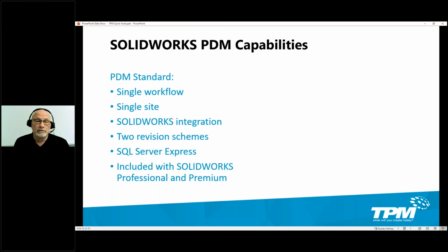It's a single site application. So if you have multiple plants where you need access, you couldn't use PDM Standard for that. It does include the SOLIDWORKS integration. It's limited to 2 revision schemes. Typically that's enough for most companies, but if you have ISO documents and you have CAD files and other documents that have different revision schemes, you might not be able to get by with PDM Standard. It runs with SQL Server Express, which is a full database, but it has some limitations. Typically for a PDM Standard implementation, this is not going to be an issue.